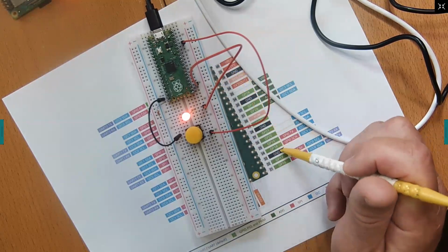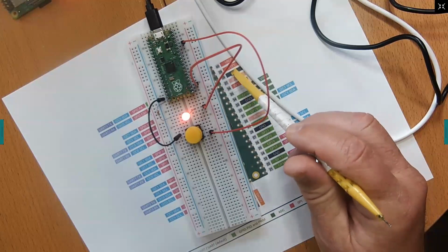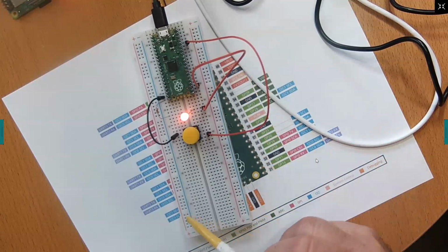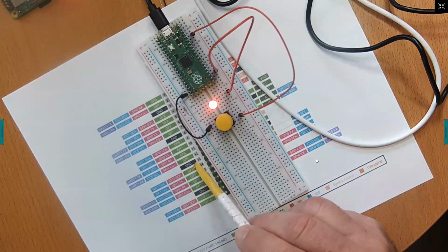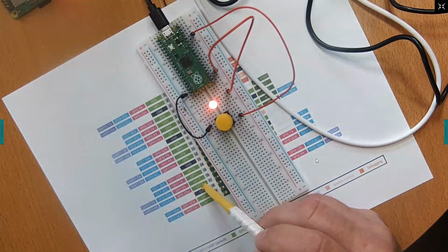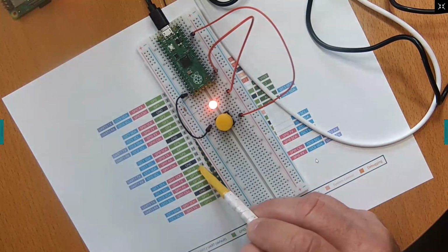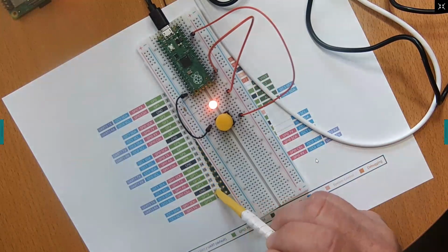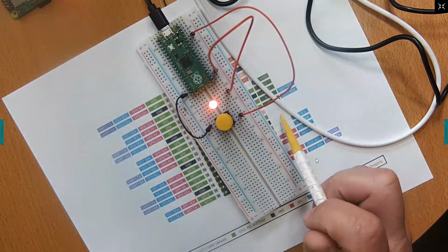And I moved it down here just to show that you can be on any of the grounds. Right? So as long as you're on any of those grounds, 18, you could put it on this right here if you wanted to. And when I say pin 14, like see right here, GP 14, that's what I'm talking about. I'm not talking about these internal numbers here. These internal numbers are the physical 1 through 20, right?